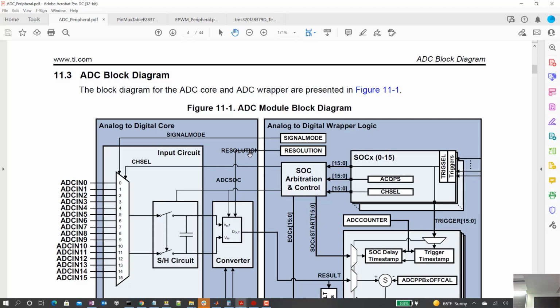Just showing you another picture here of the ADC. Remember I talked about the sample and hold circuit and then the converter itself. And we talked about how that does a little bit of a search algorithm to find the actual value that's coming in on these. This is showing it in what's called a differential mode of these pins here. There can be a 16-bit mode, which I've never done. Again, that'd be something fun to play around with in your final project if you're interested.